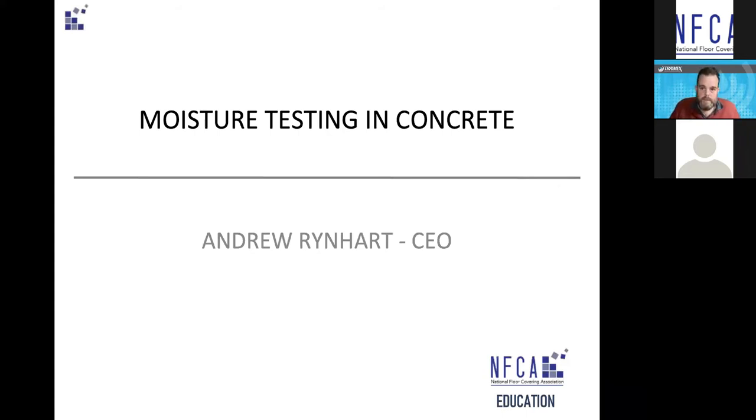So what we're going to focus on today is the difference between measuring and testing moisture versus measuring and testing vapor in concrete, because both are used. In fact, you could take the whole world of all the standards for measuring moisture and divide it up between those that measure moisture and those that measure vapor. The British standard and the Scandinavian standards are all vapor. The German standard, and a few others as well, are moisture content.